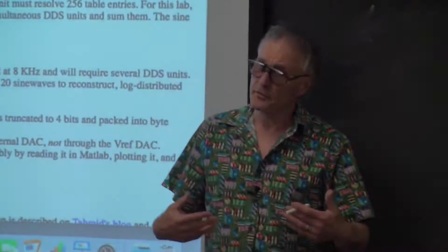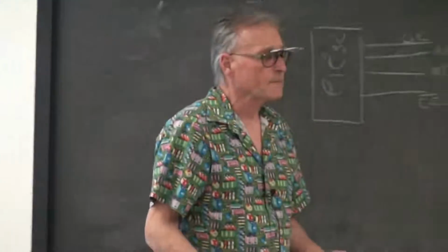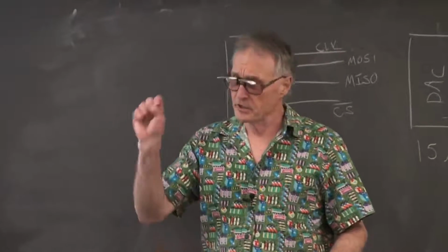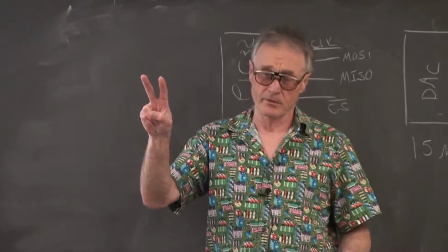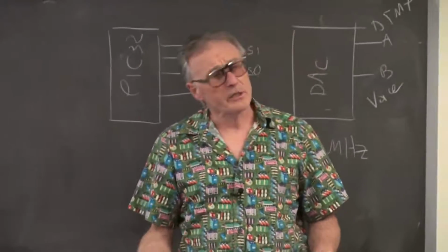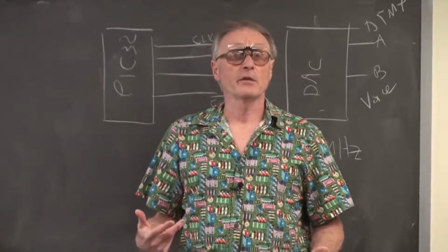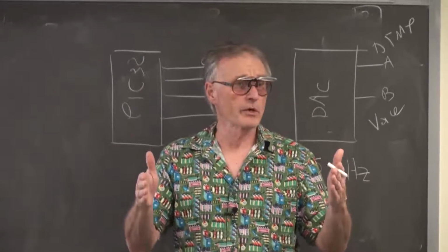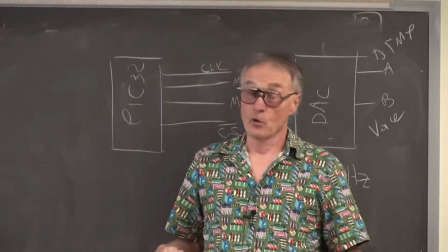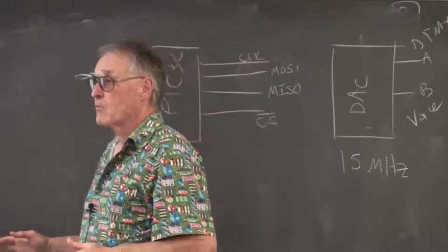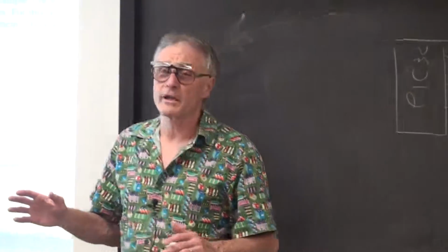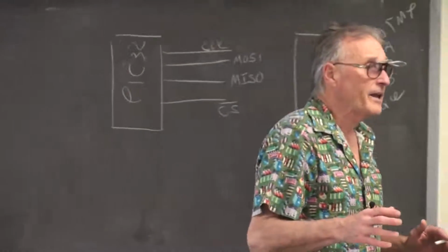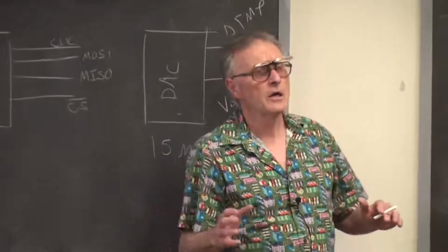My assumption, which I'm going to go through in some detail today, is that you're going to be running a direct digital synthesis sine wave generator, actually two of them, one for each of the two DTMF frequencies, plus the voice channel, all at the same rate, so that you can output all the samples synchronously from one interrupt service routine. You could, if you wanted, write 3 different interrupt service routines, all running at a different frequency, add together the samples somehow, and output them.